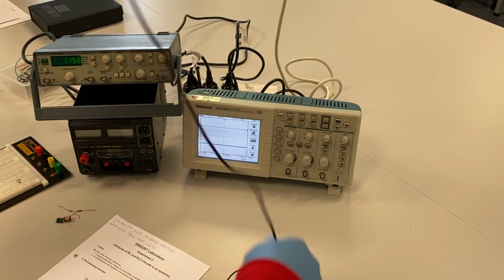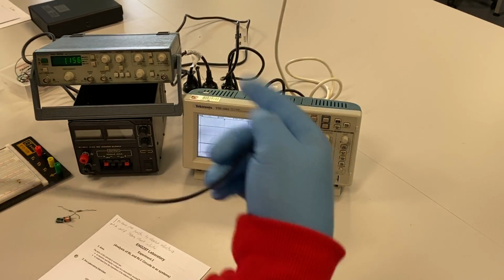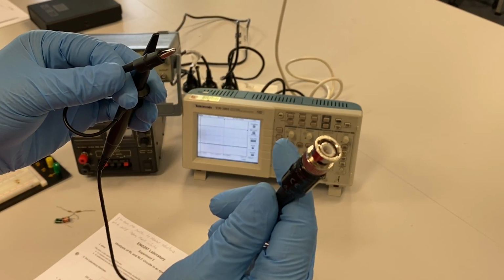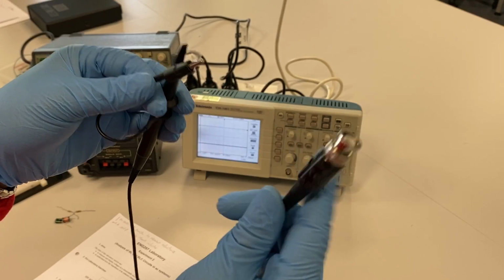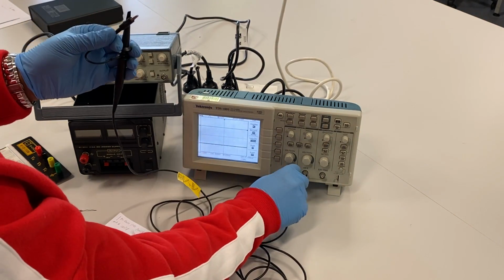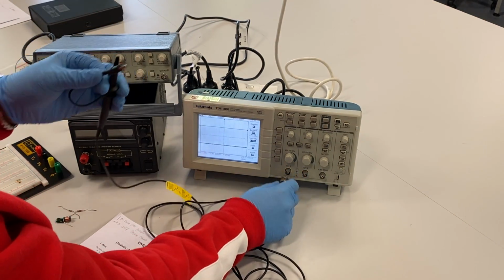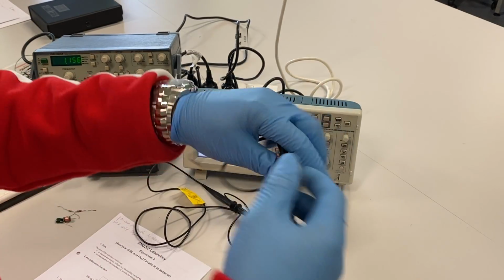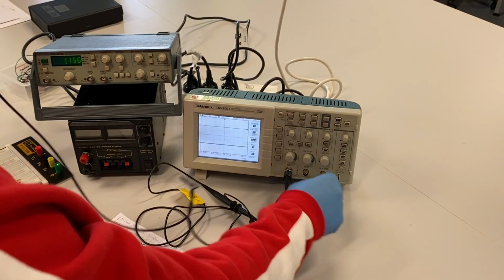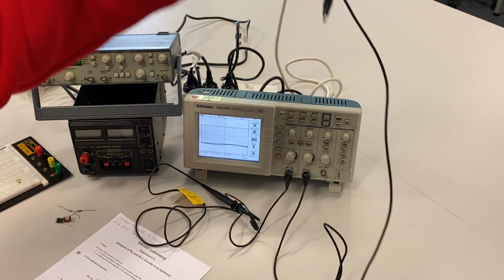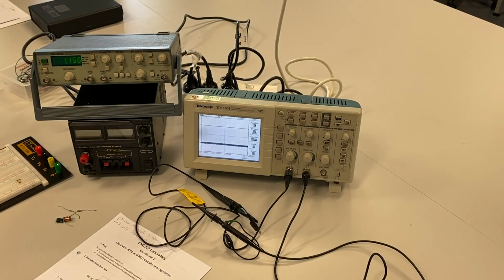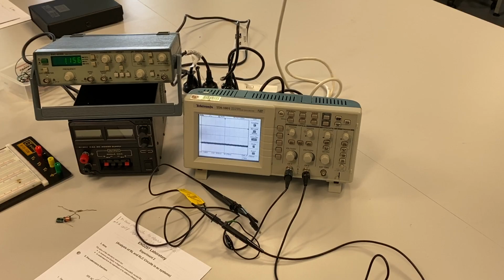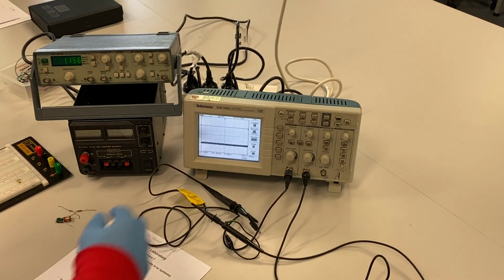These cables, and they have the other end, which looks like this, right? These cables are called oscilloscope probes. They are supposed to be on this. So we have two channel outputs of an oscilloscope. We can put this cable on channel 1, then another cable exactly like that one on channel 2. As there are two channels, we can display two signals at once on the oscilloscope. We can display the input signal and the output signal.